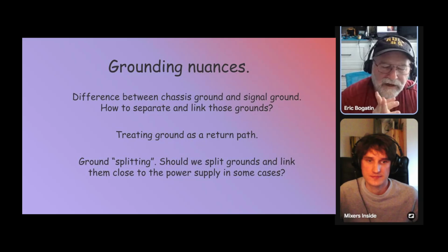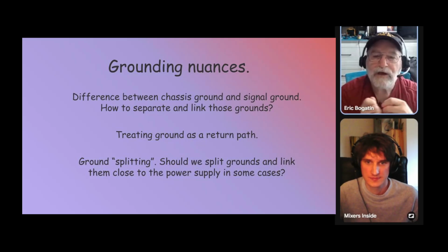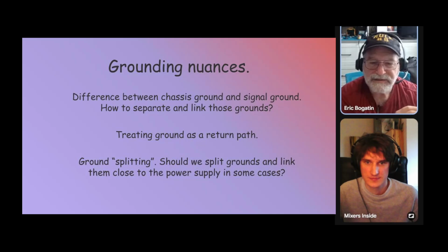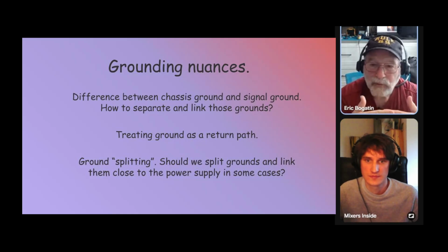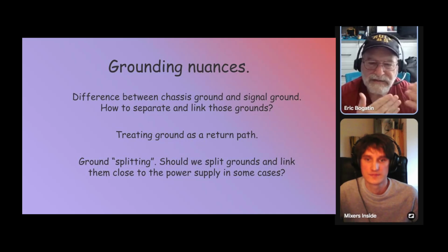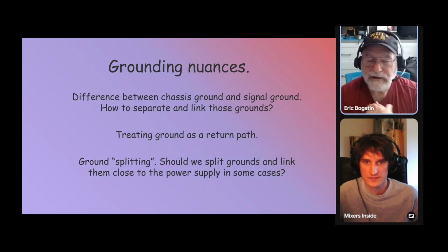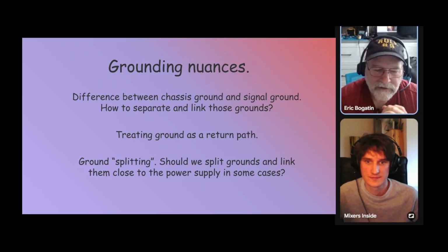And then I show an example of, okay, there are two fixes. Fix one is, I'm going to separate the returns that are used by the power rail and as the ground reference for my sensitive sensor. In the example I show, I use little temperature sensors on the board. If you separate those so that you don't have the return current in the same ground conductor as used to send the signal, you don't have that resistive noise. You don't have the IR drop noise. Perfectly fine way of doing it.